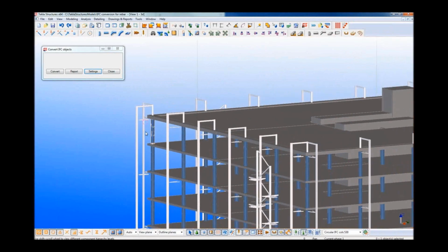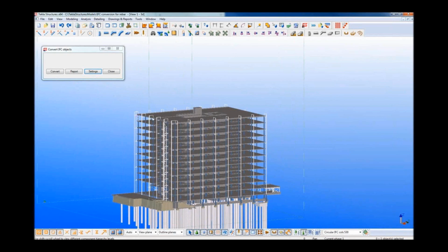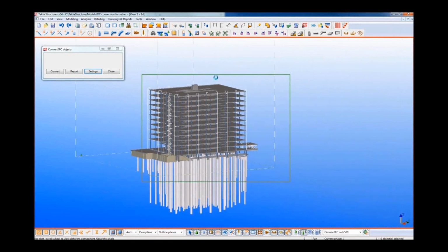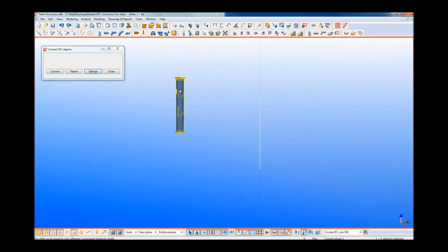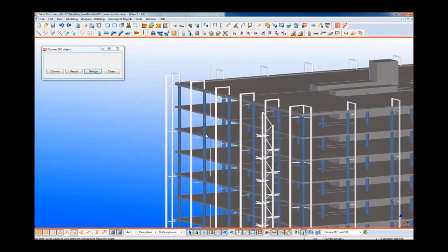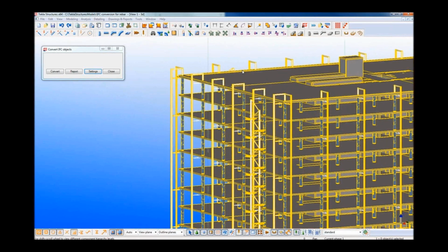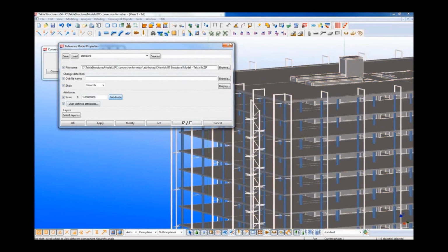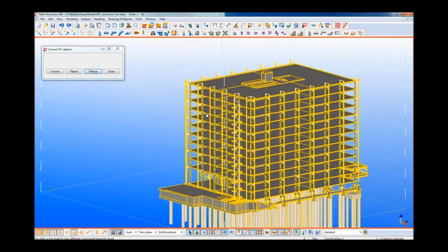And now if I window the model, it's only going to pick things that have a dimension of 530. Just the one. Something not right there. Just 1 second. I think I have to subdivide the IFC into its constituent parts. Subdivide. What that does is breaks it down. Rather than being one big reference object, it takes it into the individual objects. I should have done that earlier.